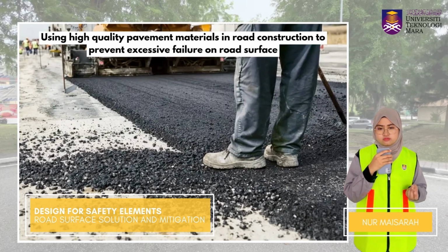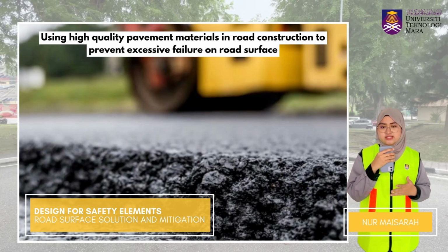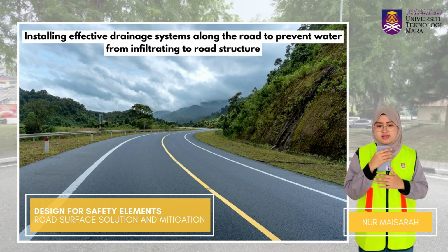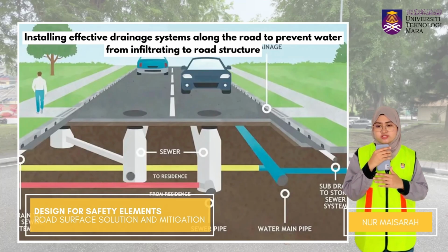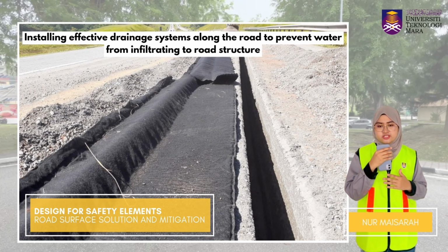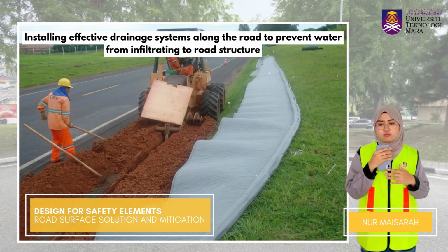Next is the use of high quality materials, which means we implement high quality pavement materials that are durable and could prevent any excessive failure in the road surface, since high quality materials have high strength characteristics. And the last one is to create an effective drainage system surrounding the area of the road intersection to help prevent water from infiltrating the road structure, which will prevent potholes and also water puddles on the road surface.